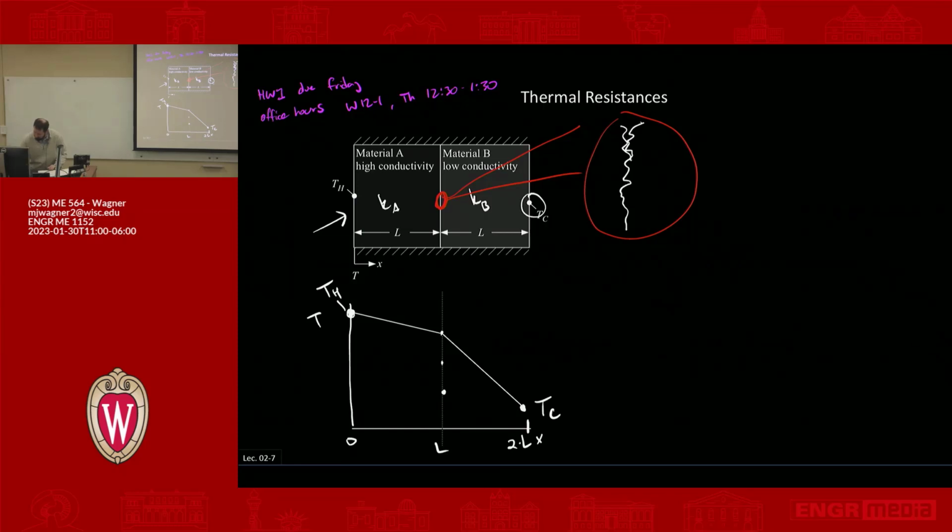You've got these points where you have incomplete contact between the two media, and you have maybe an air gap or whatever. If these are immersed in oil or something, there's some other substance coming between the conducting bodies. And that introduces something called a contact resistance.